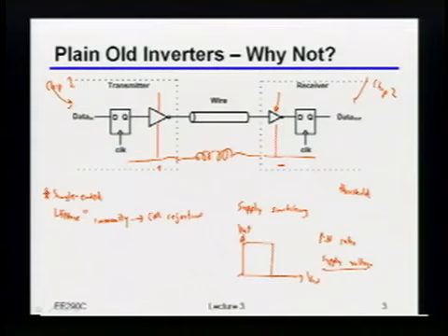And Charles, maybe you have an idea. You have that clock right there, right? So you actually might have some kind of clock feedthrough into the inverter, and then you see some spikes. That will actually change the decision of that inverter. Okay, so that's true, although, by the way, that's like maybe second or third order. I want the zeroth or first order.